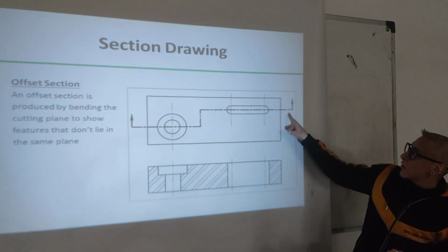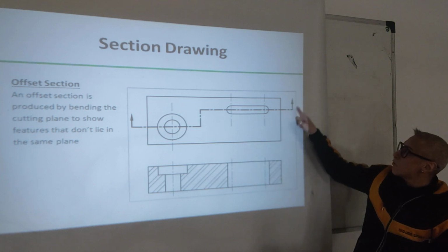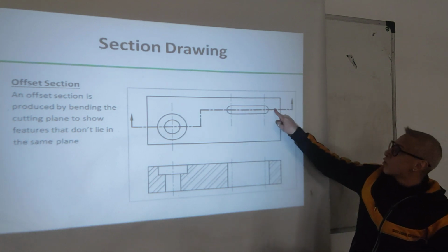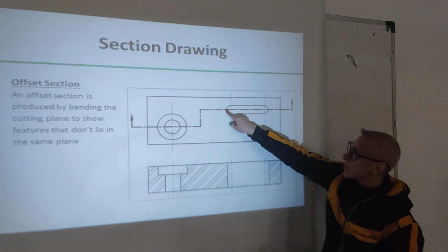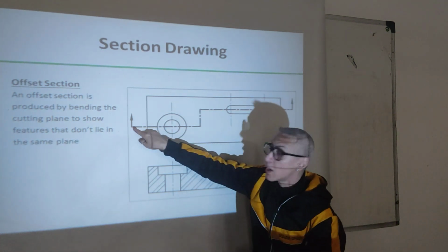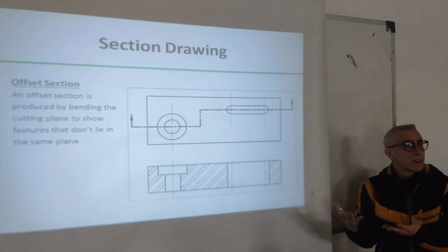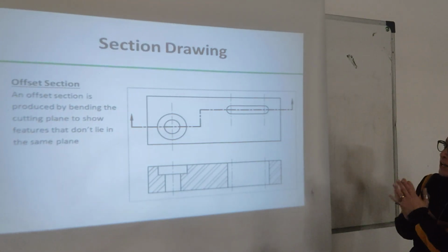But whoever looks at this understands how you cut it through. So the cut goes through here, so we can see this part here, which is solid material, then it cuts here, then it goes down. So you need to show the cutting line very clearly.